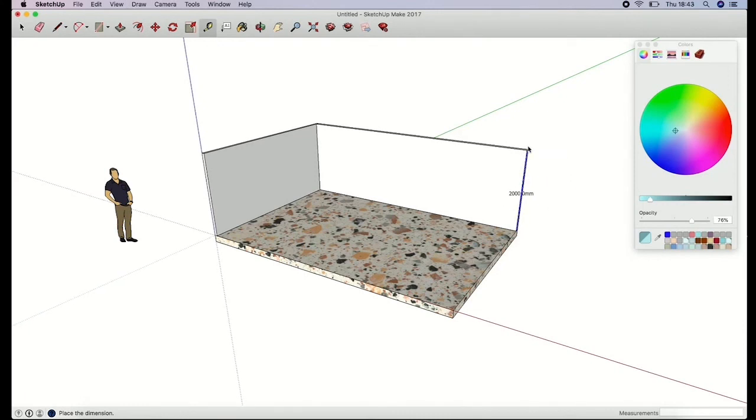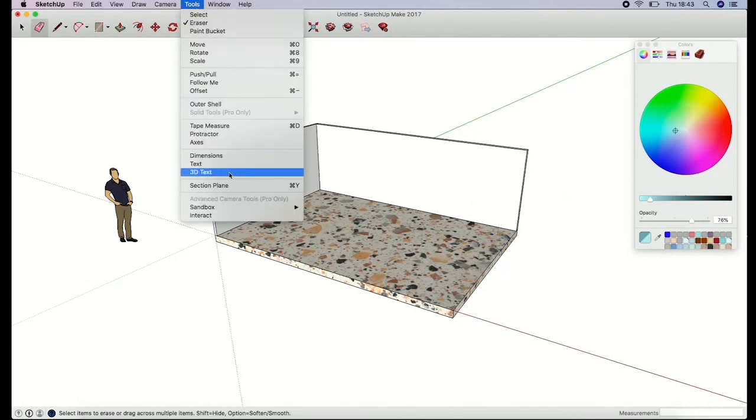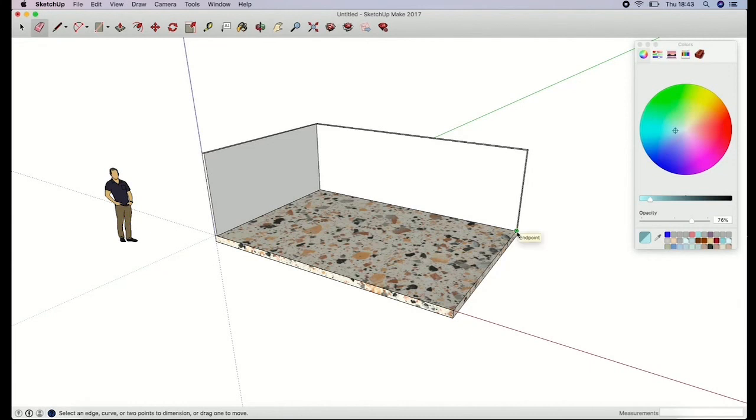The other way of doing that is, so you can leave it like that and then just click and delete if you want to erase the dimensions. If I go back to dimensions, you can also start on one side, so the endpoint, click, and then draw it to another endpoint, and then drag it out. So I'm just going to erase those.